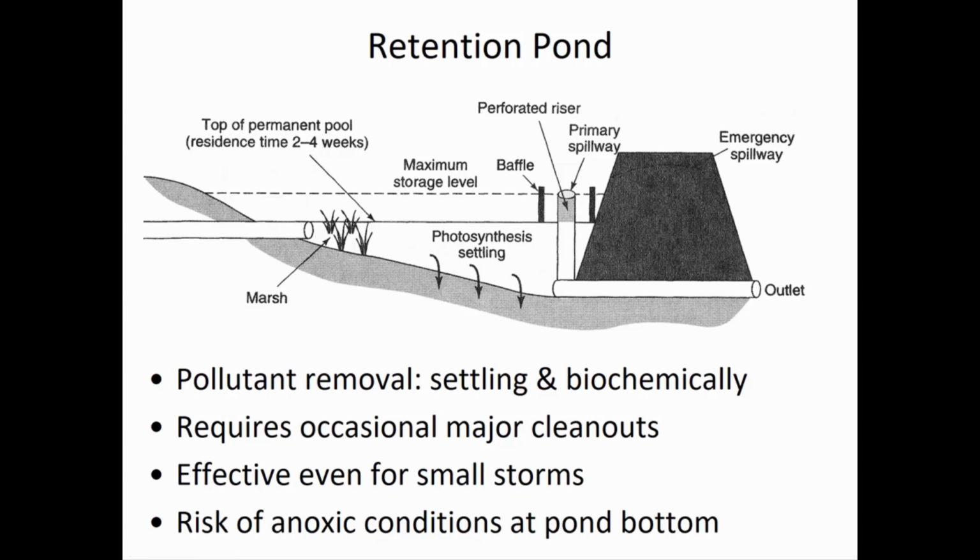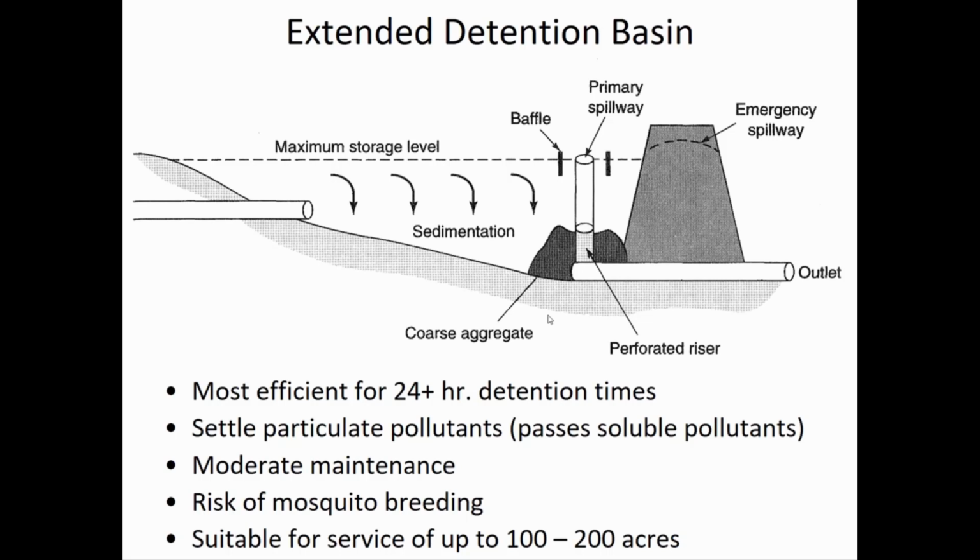But the issue here is that this extended detention basin is dry most of the time, and so it's much easier to maintain. You don't have to drain it to maintain it. You just have to occasionally, if there is a lot of sediment at the bottom, send a crew in there with a backhoe or some sort of shovel and bucket and remove the sediments.